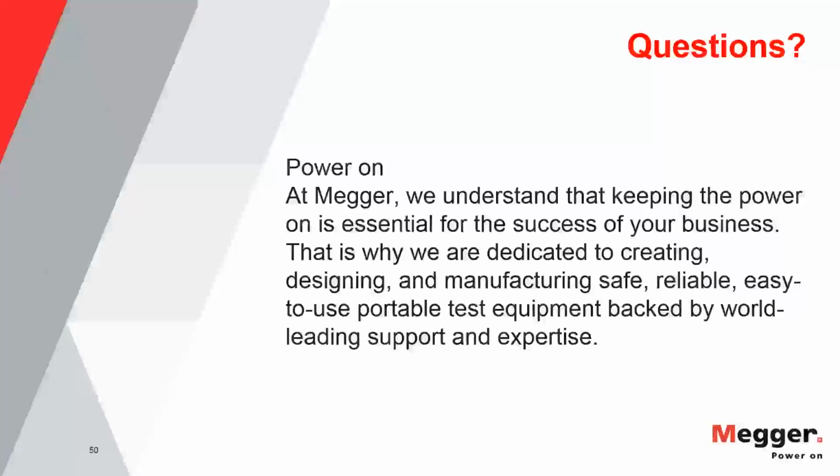For instance, one major shortcoming of online monitoring in terms of cables is that online PD is absolutely not suitable for longer cables, and most of the cables are also not accessible. That's another point. You have access to the cable in manholes at best. So yes, there is other technology available. We have some of this in our portfolio as well, but that is mainly for substation application and substation apparatus assets.